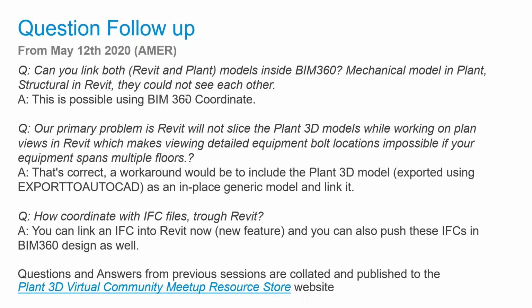Doing it with the desktop apps and doing file conversions still requires you exporting to DWG from Revit to bring it into Plant 3D, and we do recommend cleaning up your Revit models before you do that. And of course, if you're going from Plant 3D into Revit, you need to do export to AutoCAD to get pure AutoCAD solids out so that Revit can work with those.